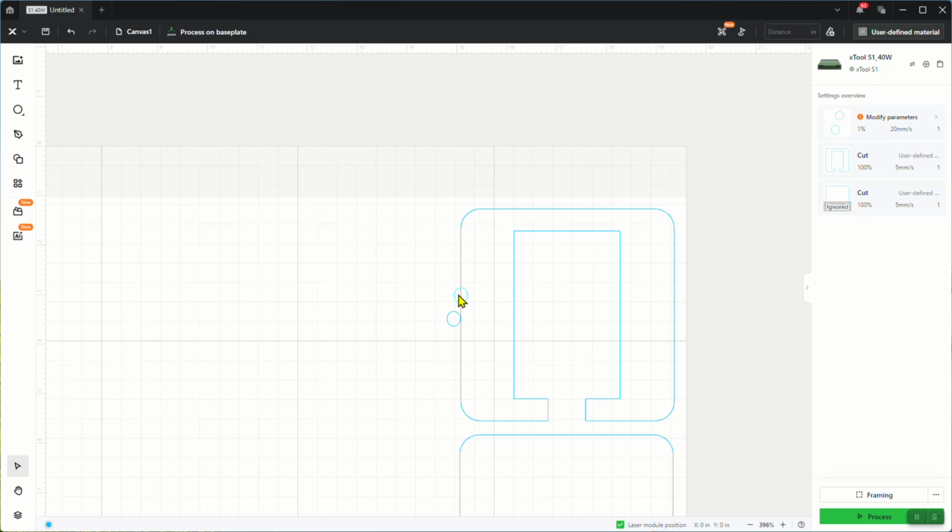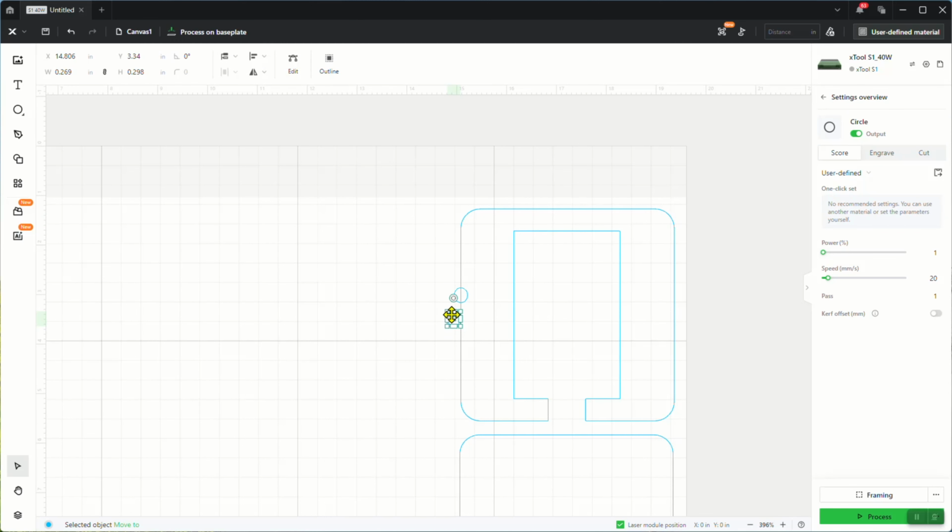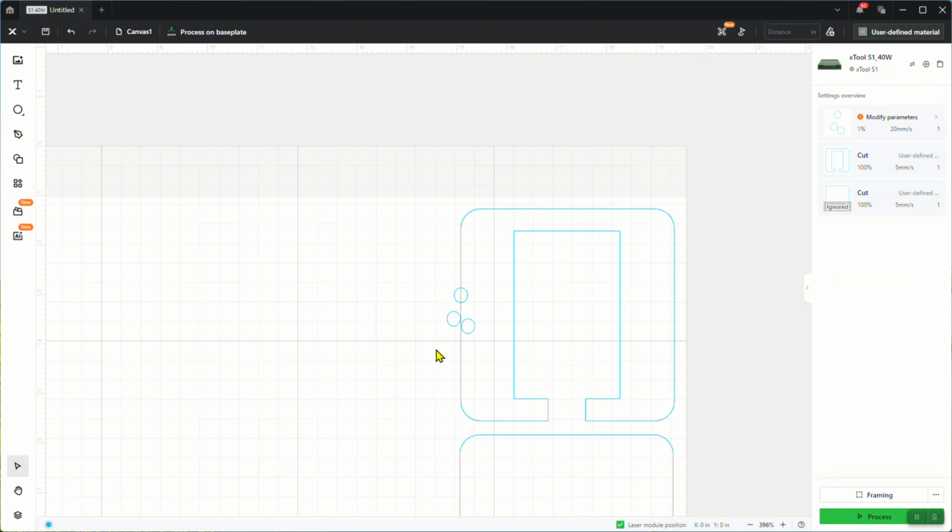So all you're doing is you're moving the center out to here, which gives you this. It puts the whole laser on the outside of your cut. Now, if you were going to do negative, then you would come on the inside. This is going to cut this all the way around like this, and it's going to be on the outside, the outside, the outside, all the way around, and it's going to come right back up to where it started.